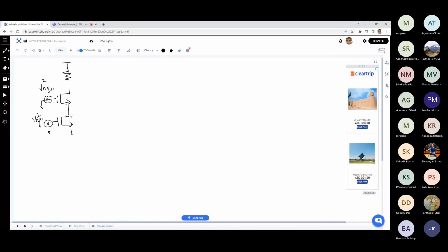So I have divided the channel current because of thermal noise divided by GM square will give you VNG1 square, likewise VNG2 square. And here the input transistor, the first transistor M1, is definitely having similar effects. So whatever we have studied for the common source, almost similar effect because this gate voltage will result in a small signal current and it will get transferred into the output voltage. So similar behavior. Whatever small signal current is produced by this gate voltage noise, it comes at the output and that basically reflects as the output signal noise. So there is no change.